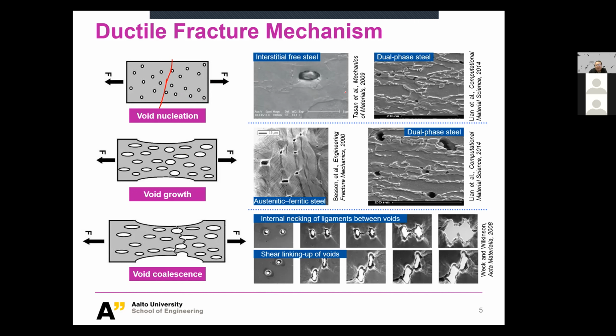Here I'm giving you two examples. The first one is so-called interstitial free steel. That means the steel is pretty clean. Not completely clean. It is clean in a way that you don't have many interstitial solid solutions, but you still have these kinds of inclusions. So this is one inclusion. And I said, they're usually ceramics and they are hard, compared to your steel matrix.